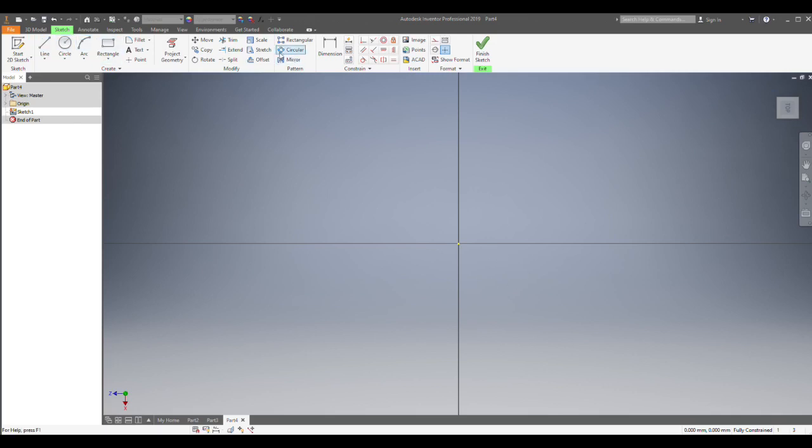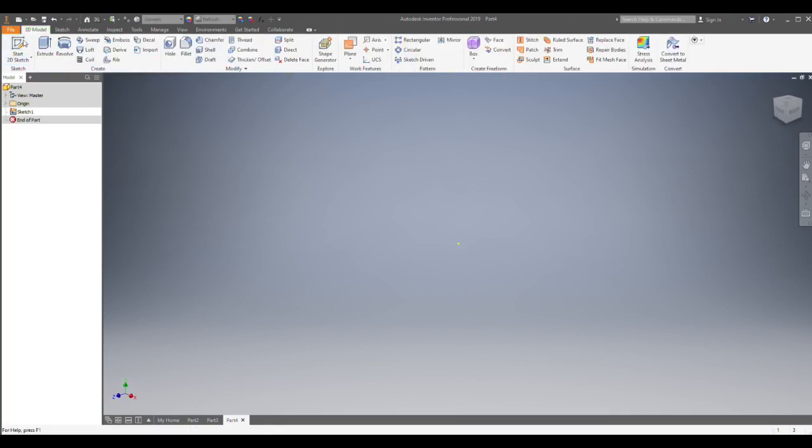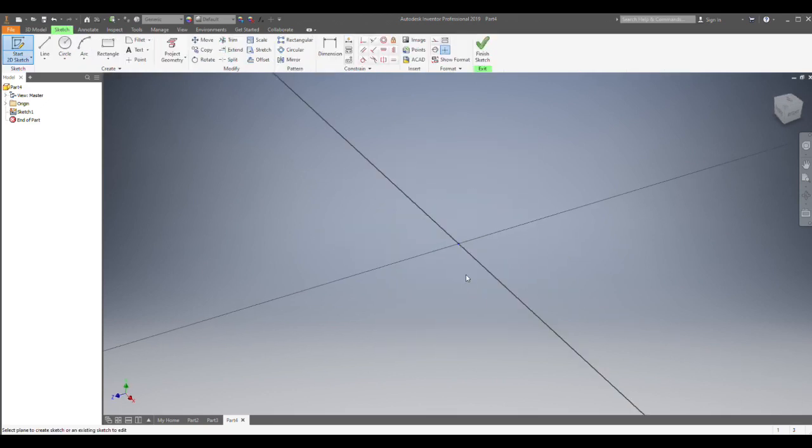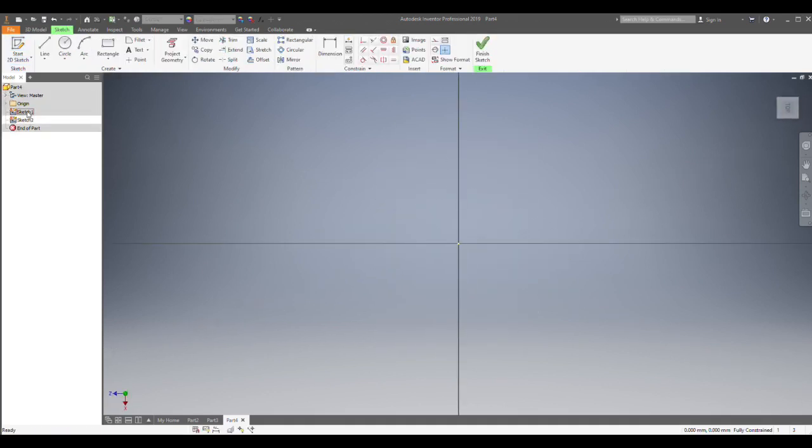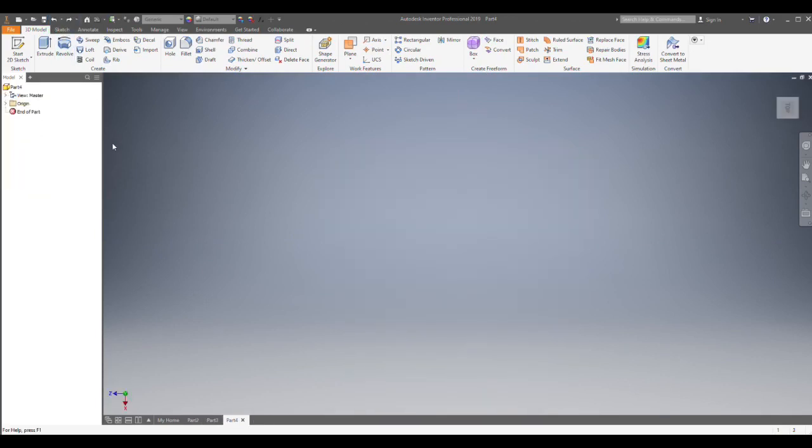Now in this sketch toolbar that we're now in, you can do a few things. So as you can see here, it still says start 2D sketch, and if I do click that, don't do this just now, it will bring up this origin again, and then I can draw another sketch, and now I've got 2 sketches up here. If you notice at any point you're maybe a wee bit stuck, it won't let you extrude something, have a wee look at your modelling tree. You might see that you've got a few sketches here, and the best thing to do is to just go back to when you had none of them, and then you can just start again. Sometimes it can get just a wee bit confusing when you've got multiple sketches.